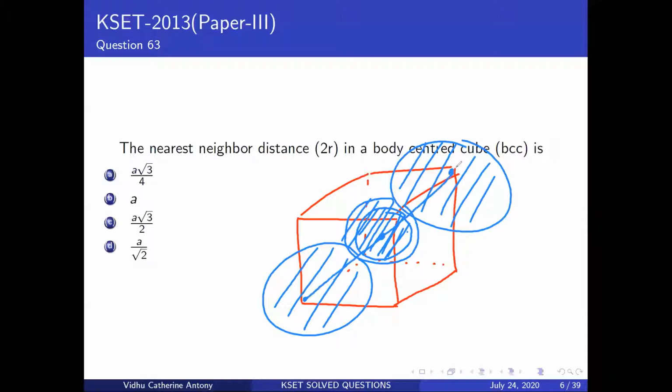Now what you're supposed to remember is if you have a cube, the diagonal from one end to the other end is given by root 3 a. You have to take that root 3 a and match it up with the total number of R's that you can find here, the radii of these atoms or molecules. So you end up having 4R is equal to root 3 a.